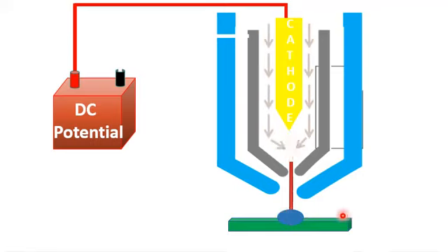However, when the spots move across, they will cause non-uniform evaporation or non-uniform formation of plasma throughout the surface of the cathode material. Secondly, there is a possibility of the spot getting out from the surface of the cathode, which will result in a non-uniform deposition of our thin film from the cathodic arc deposition process.